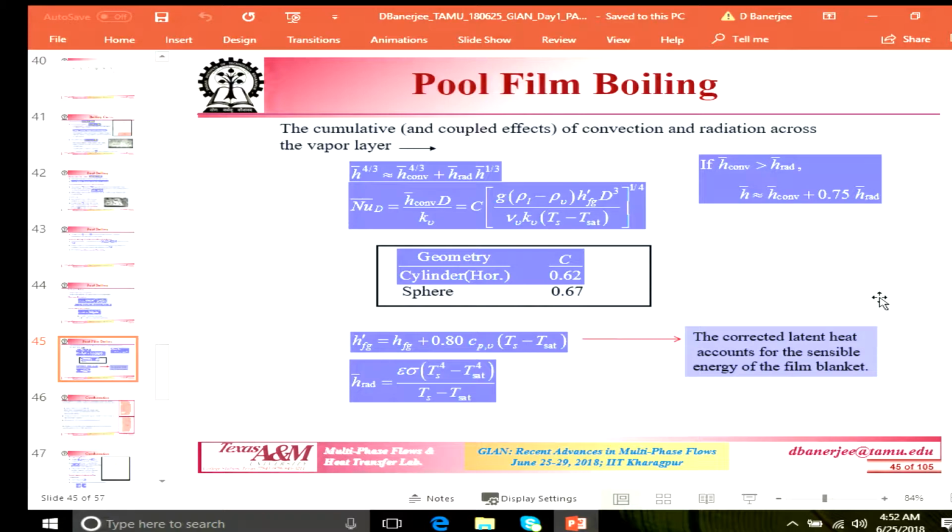So, when you write your Q equal to H delta T, that assumes that your heat transfer is independent of the size of the heater, is not it? Right, because they are saying the heat flux is independent of the area, but when it comes to boiling, the size of the heater affects your heat flux. We are going to look at it.